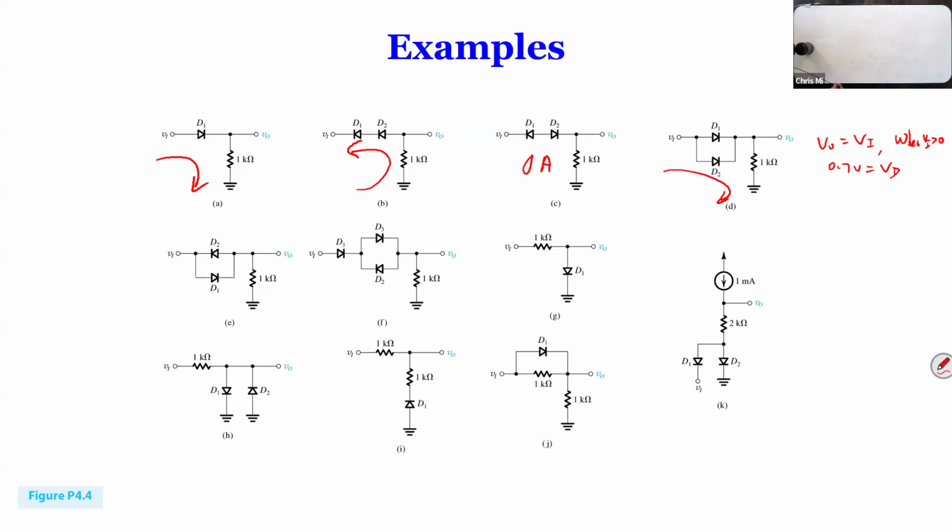Diode breakdown is about the voltage, not the current. When you reach a certain voltage, they will both break down. You're only dividing the current by half each, so it's slower in burning up. Do we combine diodes? Yes, we do. We put them in parallel to increase current capability. We put them in series to increase the reverse bias capability. You just add them.